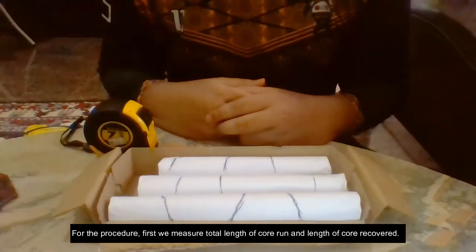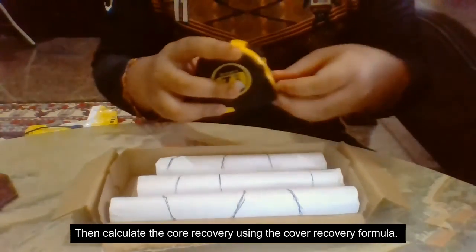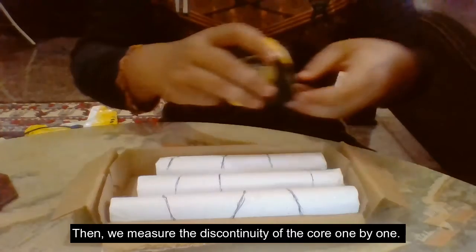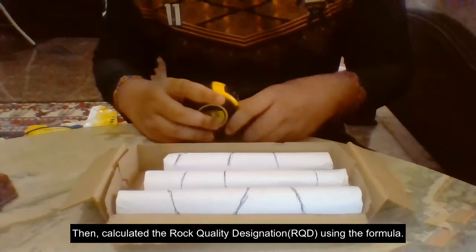For the procedure, first we measured the total length of the core run and the length of core recovered, and then we calculated the core recovery using the core recovery formula. Then we measured the discontinuity of the core one by one, and then we calculated the rock quality designation using the formula.